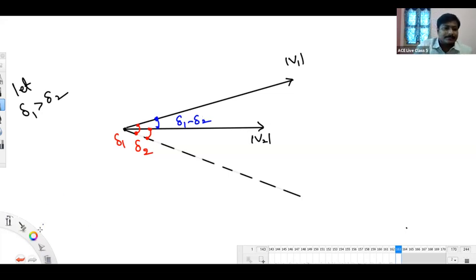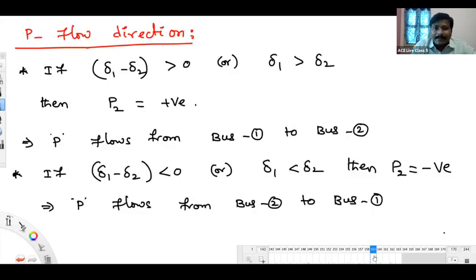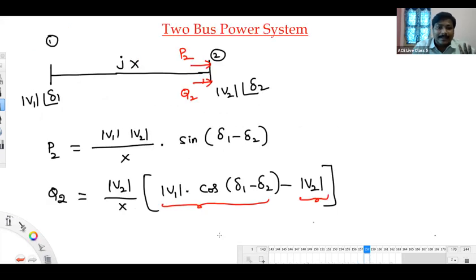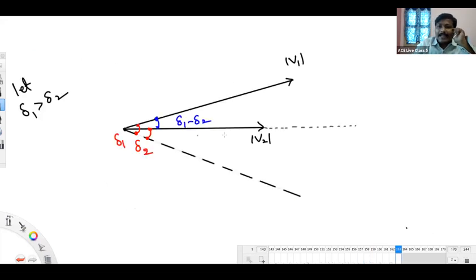Okay, next. Listen all of you, kindly don't confuse. I'm asking one very simple question to you. On which bus are we standing and discussing real and reactive powers? Please tell me. Bus 2. That's it. So I have taken the bus 2 voltage as a reference, because bus 2 is the bus on which we are standing.